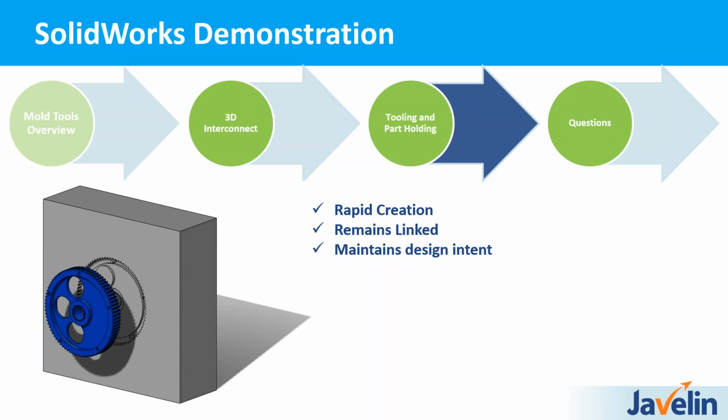And also we have the option to update. So unfortunately I wasn't able to show it, but we updated the one file. I had the other one still open and it hadn't updated yet. Basically it gives you the option of when you want to update that part. It does the initial import when you first open the file, and then it makes it into a SOLIDWORKS document, so you can keep it at that state as long as you want if you got new models from the customer, or if you wanted to update your models, then you can basically pick and choose when that'll happen.